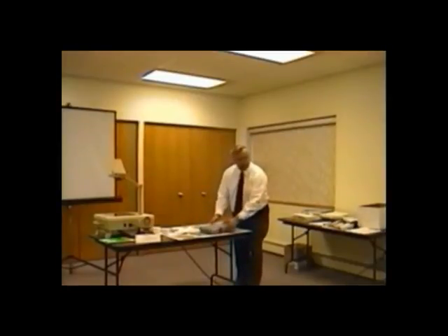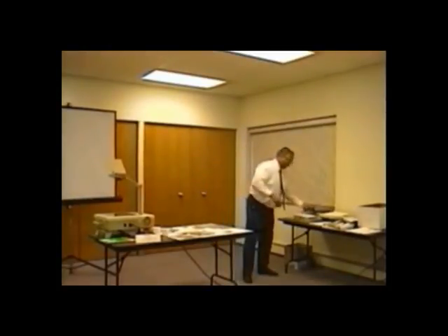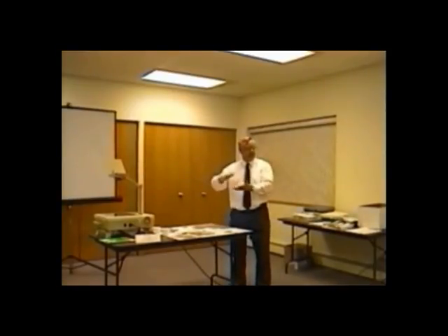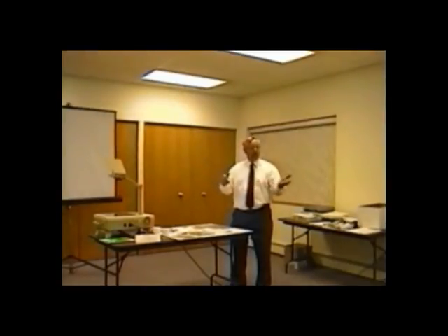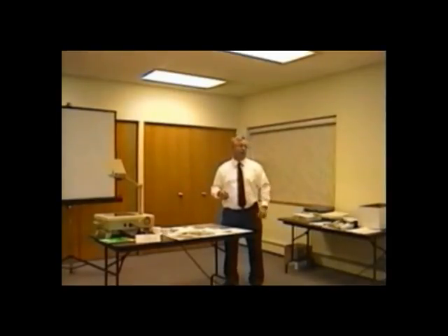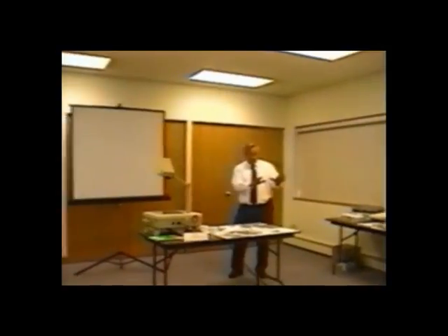Okay. So again, you now know what the scale looks like. Now we're going to show you how to use it, and of course, at other classes we can demonstrate that. But if you put your recovery tank on there, all you do is zero it. You recover back into the tank, and then it shows you exactly how much you recovered. If you start to add gas and you say, I want to put in 51.7, you start adding the refrigerant by whatever method. The methods are put it to the high side, not running, or low side, running. And you just keep letting the refrigerant go in until you reach your 51.7 ounces. Okay? All right, so we okay with that so far?